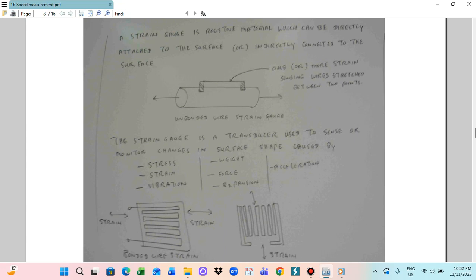So you should use the appropriate operational amplifier. The change of the stress produces a current, and the current value is the signal value. This will be small, so the small signal value has to be amplified. So we use the Wheatstone bridge and the amplifier to enhance the signal produced by the strain gauge. This is called a strain gauge circuit.